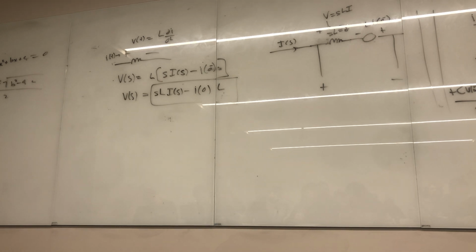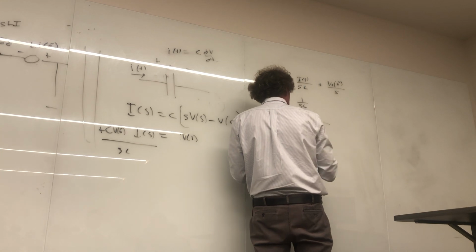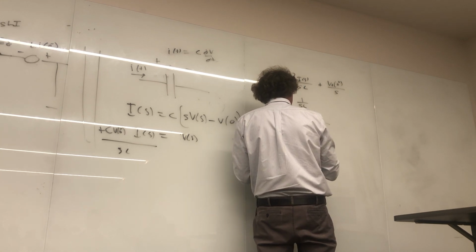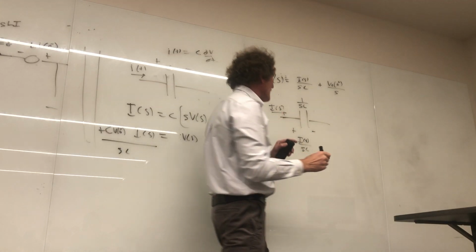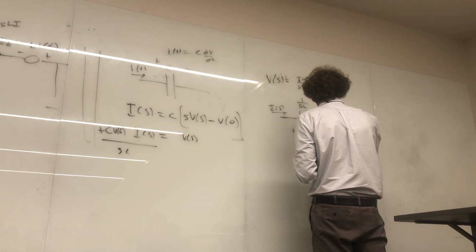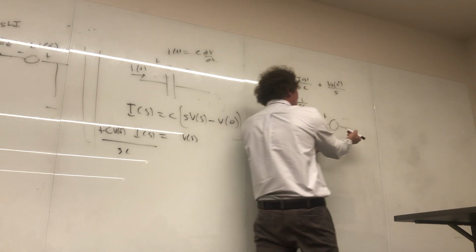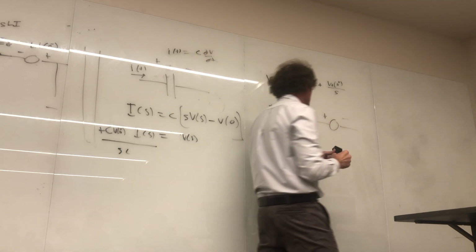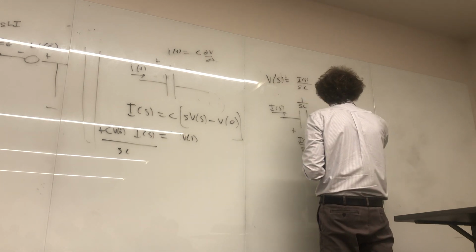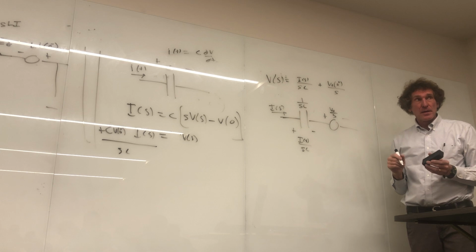What you can do is think of it as this. You think of a capacitor as having an impedance here of 1 over SC. We're assuming an I of S is coming. So the actual voltage across just that capacitor would be equal to I of S divided by SC. Are you with me on this, class? Then you put the voltage source. This voltage source is additive, so it's plus to minus. It has the same sense of polarity as the capacitor. It's plus to minus here, and that voltage is just V naught over S. All right? Everybody got me?